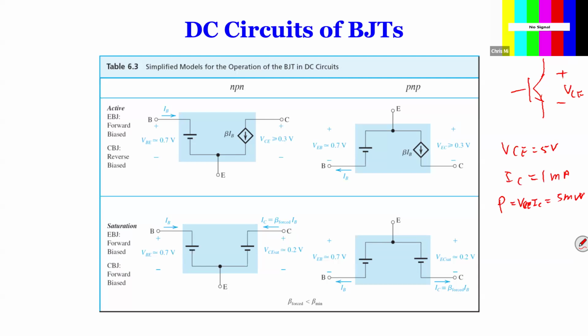Okay, what I wanted to talk about is not this, but the nonlinear operation. Now, let's say VCE is 5 volts and IC becomes, say, 100 amps. You ask, why 100 amps? Well, if you have a big solar panel and you want to convert the electricity to AC to connect to your house, you need a lot of current. That could come to 100 amps. So now your loss is going to be 500 watts: 5 volts times 100 amps gives you 500 watts. If you have 6 of them, that's 3 kilowatts.